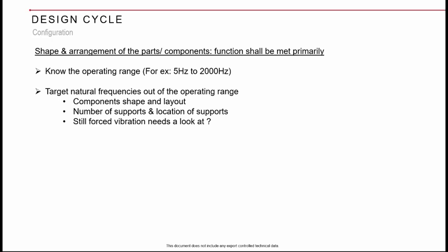It may not be resonating, but it will see the same excitation acting as a fully reversed stress state. So maybe you can just do a static analysis with the excitation levels applied, but you should consider that as a fatigue level, fully reversed fatigue.